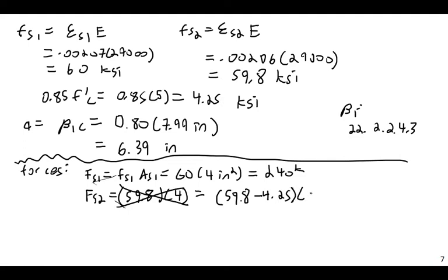And this will keep me from double dipping, basically, times 4 inches squared. Again, this is the actual stress I would predict in the steel there based on its strain level, but the concrete. I need to adjust this so that I am not double dipping. An alternate way to do this would be to reduce the effective area of the Whitney stress block. But mathematically, it's the same thing no matter what you want to do.